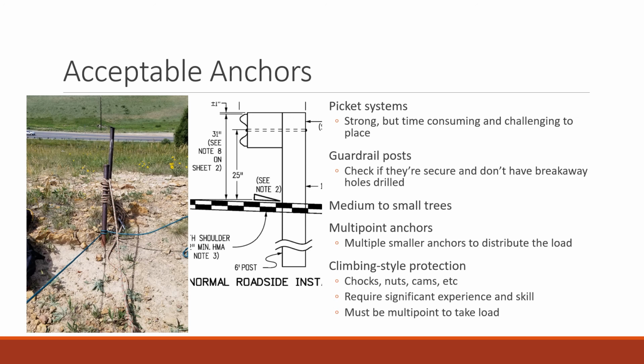Make sure that they're in the ground, make sure they're alive, make sure they're healthy, and that they're not moving if you kick them. Go real low on trees if you can. You're going to want to also consider multi-point anchors. They take more work. They're more complex. You've got to think about the angles that are involved to make sure all the tension back ties are working effectively. They're a great option if you don't have any really good anchors and you're going to distribute that load between smaller anchors.